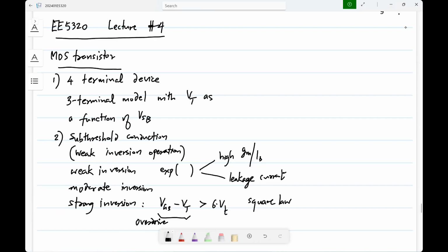At the same time, if you have a higher threshold voltage, the maximum current that you can get will be smaller, so the speed of the circuits will be less. Especially when you come to very small supply voltages, 1 volt or under, you will need these options, because when you had high voltages, you could have a single transistor and then use a variety of circuits to get what you want. But here you will need that.